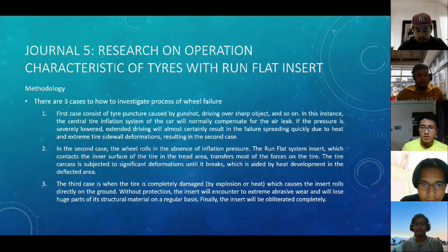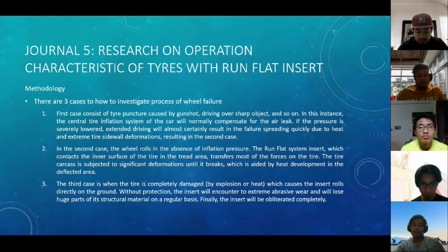In the second case, the wheel rolls in the absence of inflation pressure. The run flat system insert will contact the inner surface of the tyre in the tread area, transferring most of the force on the tyre. The tyre carcass is subjected to significant deformation until it breaks, which is aided by heat development in the deflected area.